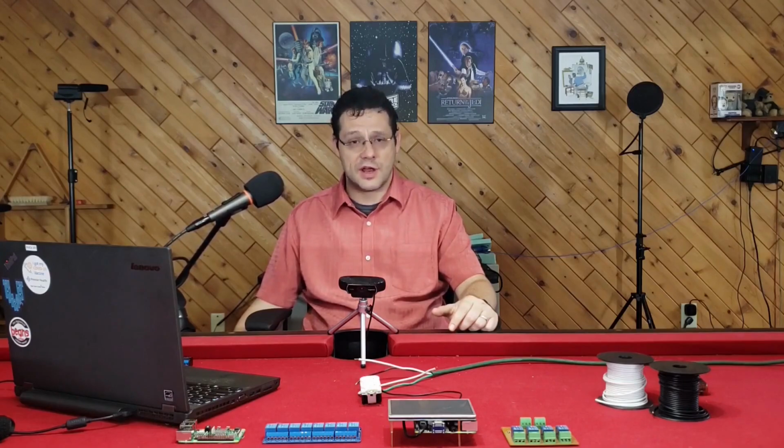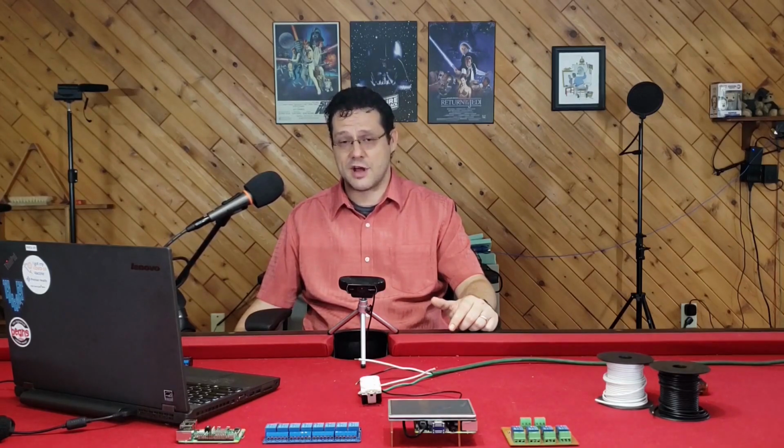You do not have to connect a switch to these relays, and I don't in my system because I don't need to. I also want to point out to those viewers who may be following this series to update their old low-voltage systems, do not use your original momentary switches for these relays. It might work, and it might not be terribly unsafe in many cases, but I would not recommend it given the age of these switches, as well as the possibility that the wires or switches themselves are not rated for the 120-volt power, and they are not protected from overcurrent in any way.